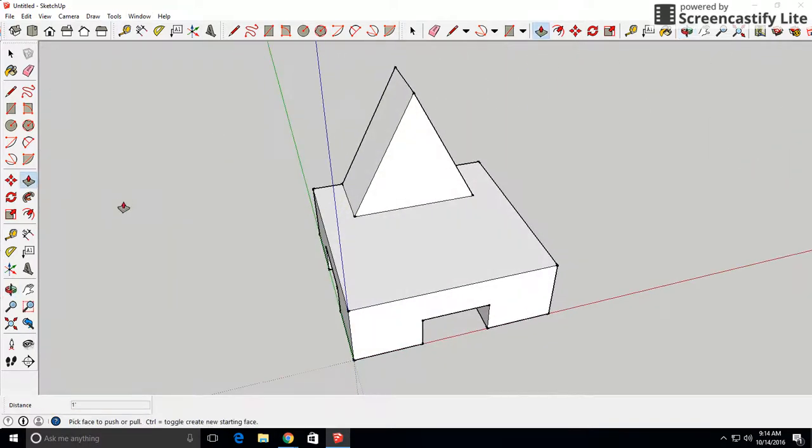Now that we have a triangle, we can push-pull this out a distance of 1 inch, and the triangle feature is done. Now we've got the rectangle that lives behind the triangle here, so I'm going to sketch that out on the surface. The one corner of that rectangle comes from the midpoint of this triangle feature, so I can click here at the midpoint and come down a distance of 1. Bring that line to the edge. Then I need to complete that shape.